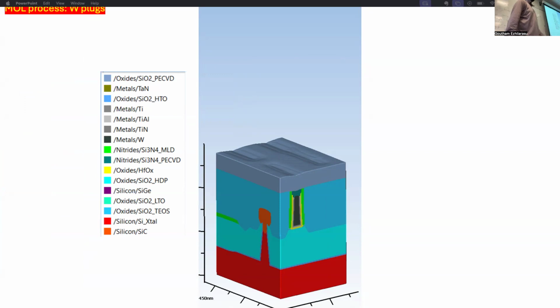When we etch down to make our contacts, is there any rule that we use to figure out the sizing of the mask for the contact? That's in the design rules, usually. The design rule will tell you what the contact size is. So if the polysilicon is some size, the contact has to have some distance from the edges. That rule will be there in the design rules.